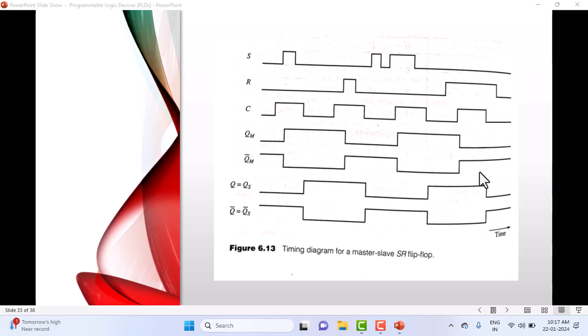Again one here, then 0, 0, and it continues 0, 0. No change state only. The no change state will be continued. So here, for some time it is 0, 0. No change, that means 1 will be continued here. But look at here now, R becomes 0 now, both are 0, 0. Now what happens? Your clock is still enabled, 1, here. Because of 0, it falls here. You can see it falls here and it continues now. Understood this? Any questions?